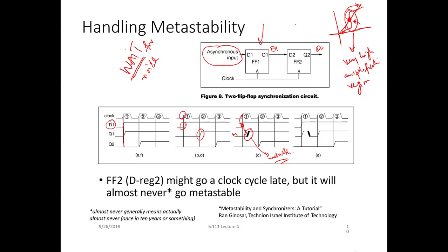And these synchronizers, what are these flip-flops doing? The first synchronizer introduces a wait of 1 cycle. The other one introduces a wait of 1 more cycle. So overall, here you are waiting 2 cycles. Whenever you insert a flip-flop, you are introducing a delay of 1 cycle. So if you want to reduce the probability of metastability, you can increase the number of flip-flops in your synchronizer.